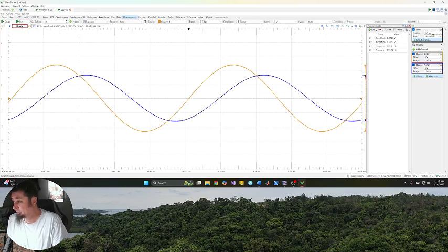Next, at our scope, we're set at a time division of 200 microseconds. Channel 1 is at 1 volt, channel 2 is at 2 volts, and then for our measurements we have our amplitude here and here for C1 and C2, and our frequencies both at 1000. When we go to run, we make sure our buffer is at 100, just because I like it there. Next we start both wave gens up and then the scope. We get our nice little wave right here. Go ahead and stop both now that we have our waveform up.